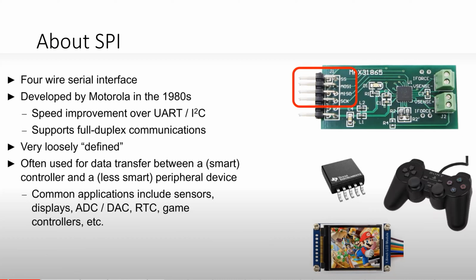So start bit, address, and then acknowledgement. In the sense, when this address hits the particular slave, that slave will give some kind of acknowledgement: I have attended, I'm ready to transfer the data and ready to receive the data. That is the acknowledgement given by the receiver to the sender.